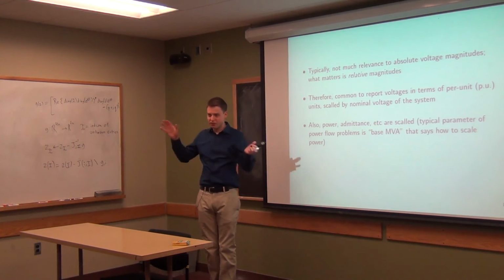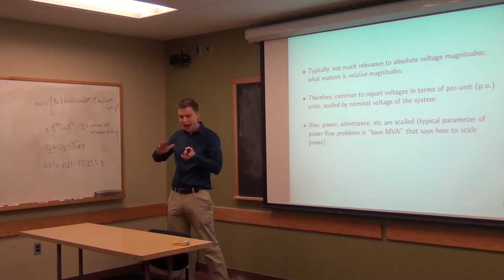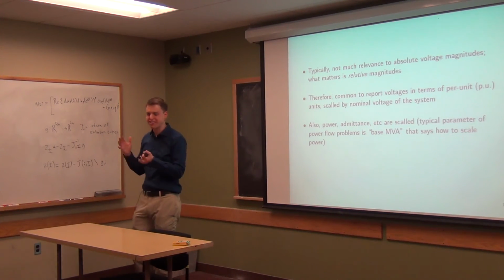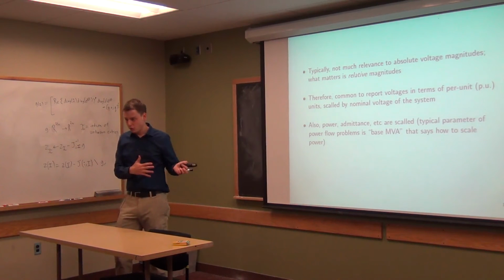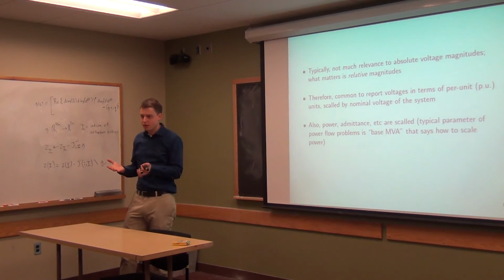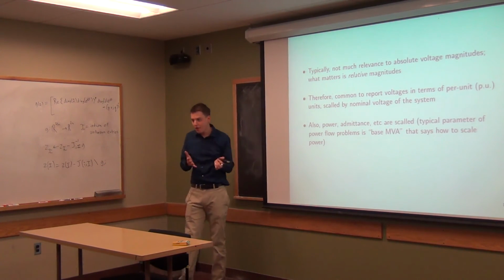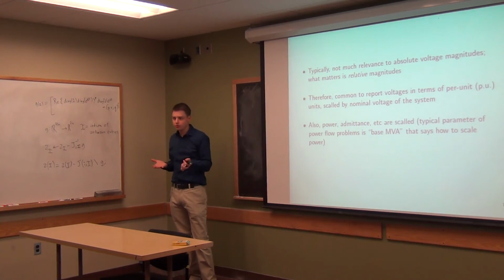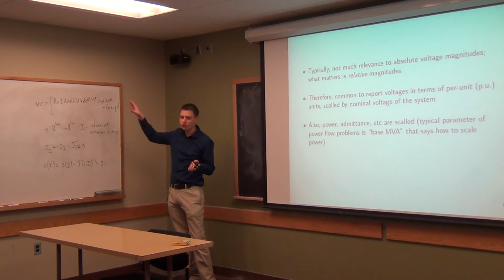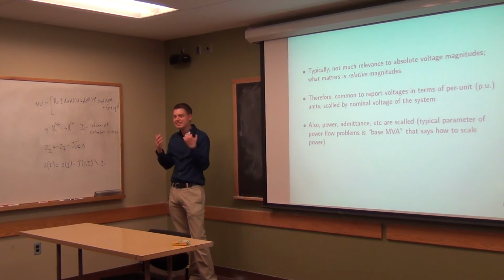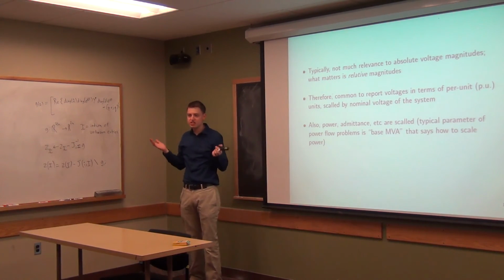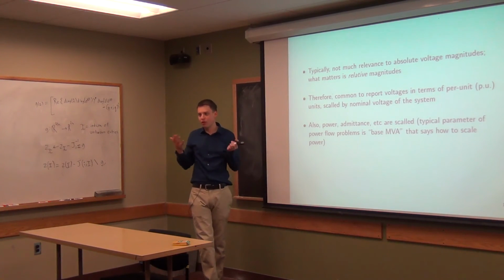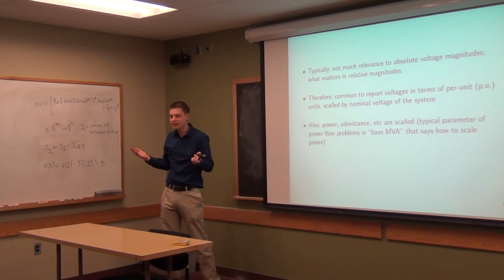You might have really high voltages, high powers, really high values on your network. But typically, you don't really care about the absolute values, right? Yes, if you're worried about knowing the actual voltage for safety reasons, that's fine, but it's easy to scale these things. And making them big just makes the numerics less stable. You're going to run into more issues like numerical overflow.